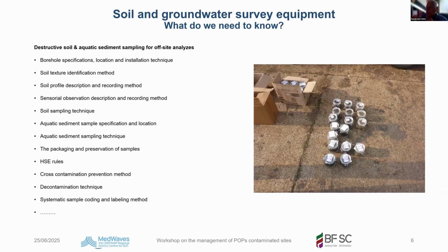Destructive soil and aquatic sampling for off-site analysis. Borehole specifications, location and installation techniques should be recorded on your bore log. Textures being identified, soil description and recording the methods, sensory observation and description and recording the methods, soil sampling technique, aquatic. So you need to know the soil sampling technique, the aquatic sediment sample specification and location, the technique for sampling bottom sediments, also called aquatic sediments, the packaging and the preservation of the sample.